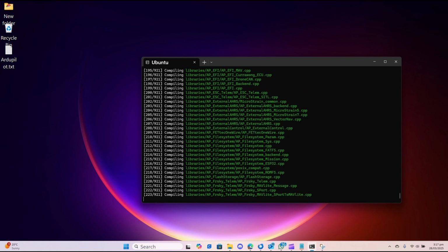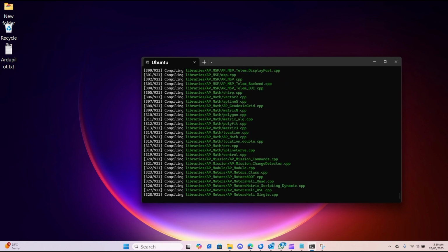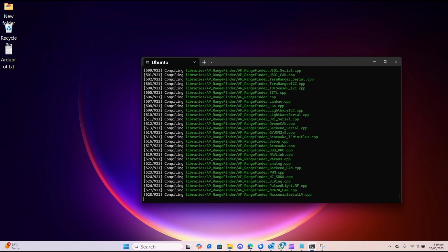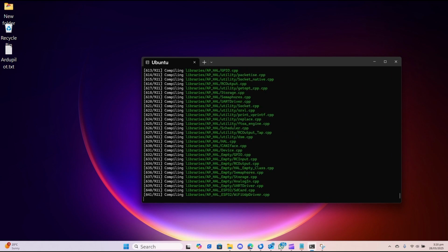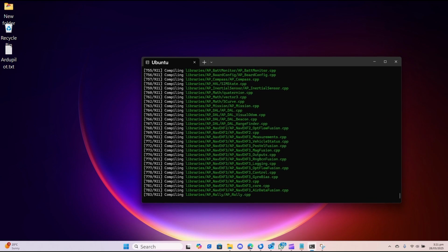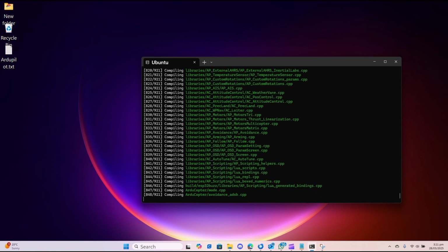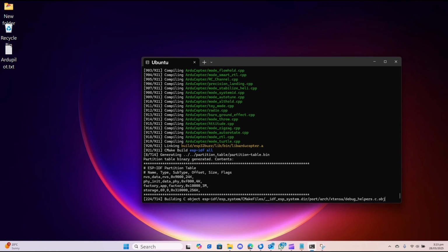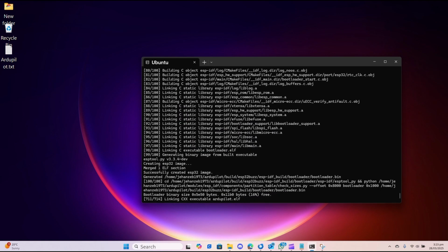Later on in the Mission Planner, we can select what type of copter this is. Is this a quadcopter, a hexacopter, or different configurations that are available with Ardupilot. But the same copter code works for all of them. So we only need to compile it for copter. Similarly, if you are doing it for an airplane, you can compile the code for plane. Again, we've sped it up because this process sometimes takes long. And now it's generating an ELF file.